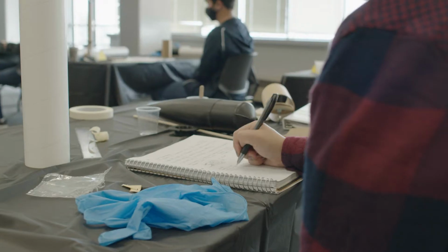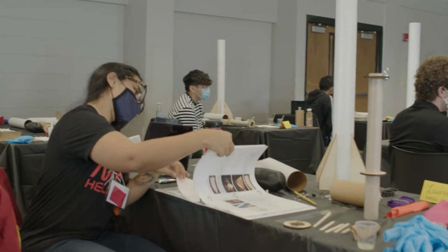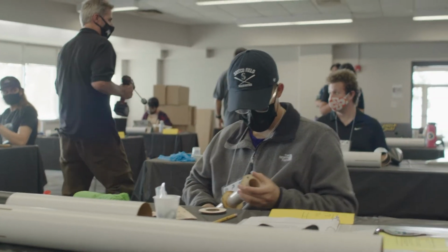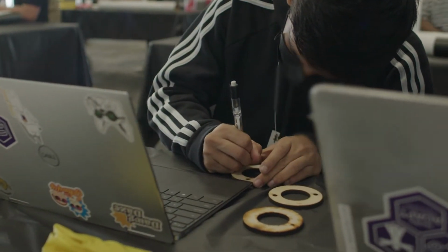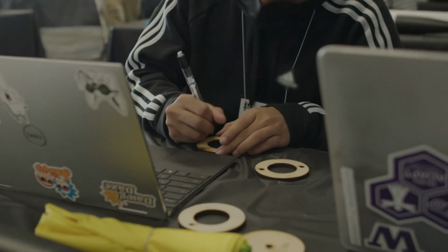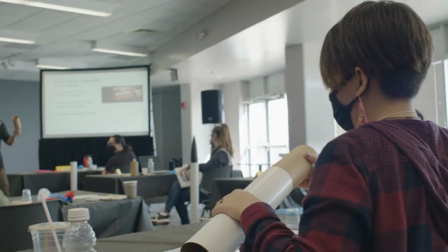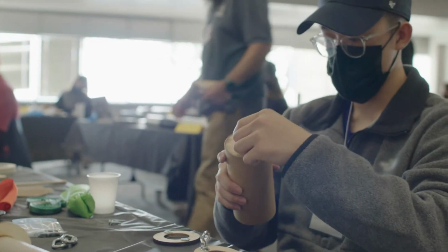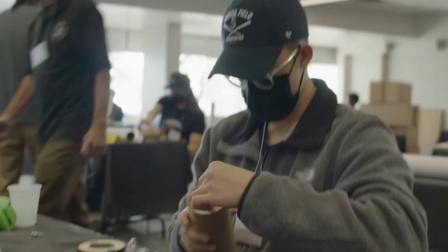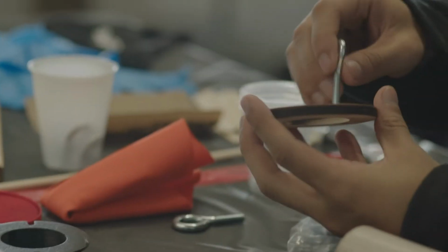While building, be sure to take notes, read all instructions carefully, and dry fit every part to determine if adjustments need to be made. Label everything. Some parts appear identical, but as you drill holes or make cuts or modify components, there will only be one way it all fits back together perfectly. Many teams have prepped their rockets only to discover that their holes don't line up properly.